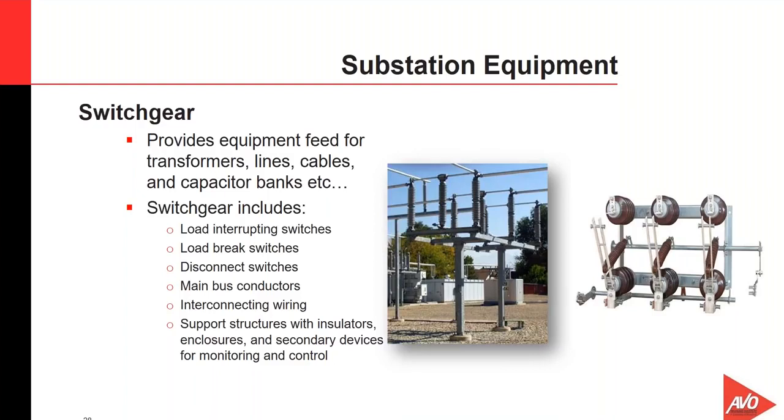Switches that are used for isolation, load interruption, and transferring service between different supplies. Okay, let's see, what else can we talk about? Load interrupting or load break switches combine the function of disconnecting switches and a load interrupter for interrupting at rated voltage and currents not exceeding the continuous current rating of the switch itself. Most of the time, you may see automatic transfer switches out there. They're double throw construction. They're usually used for emergency and standby power generation systems rated at 600 volts or lower.